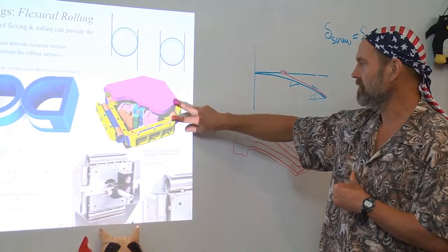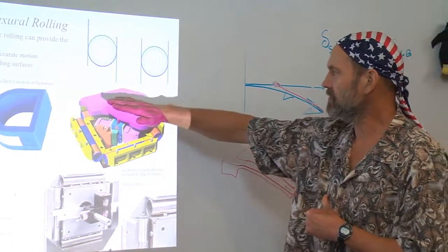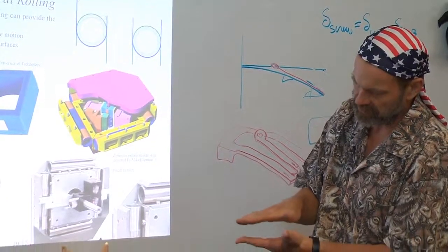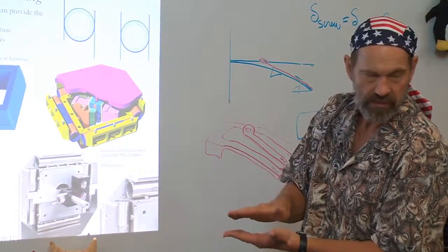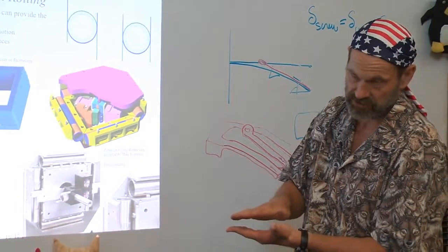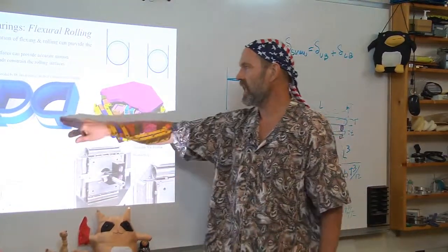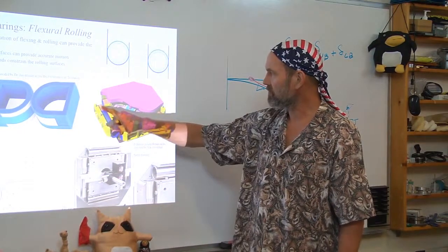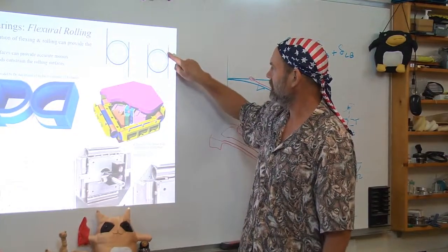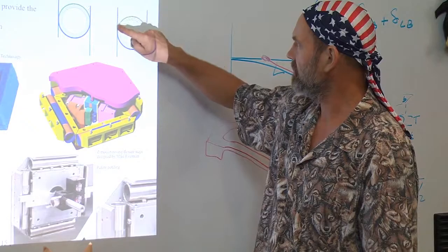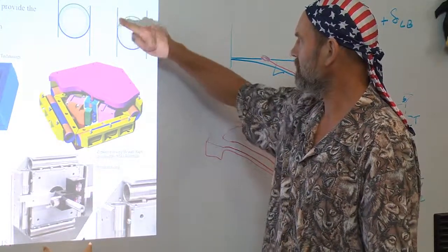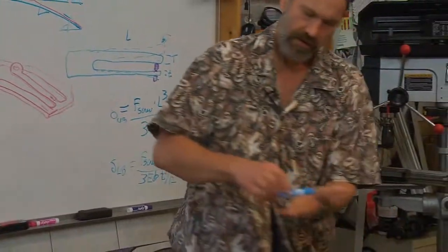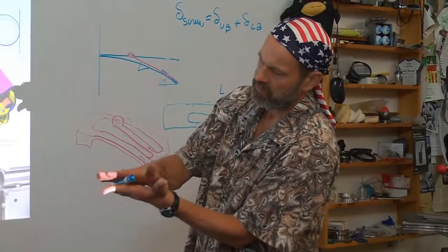This type of structure here, designed by my friend Mike Everman, this is a cutaway view for a stage that moves up and down, small amount of motion, but has extremely high pitch and roll and even yaw stiffness. And it uses this same effect through, notice these copper-colored parts here. Here's this green bearing coming around, and the blue one coming around.